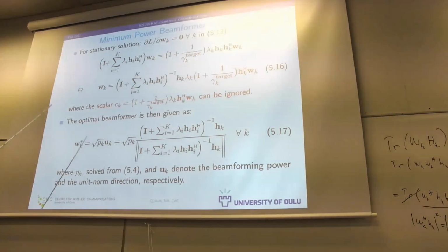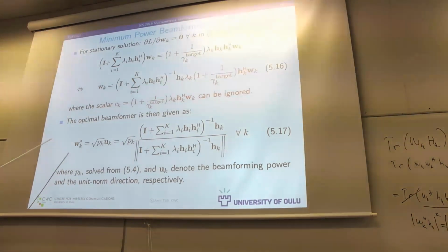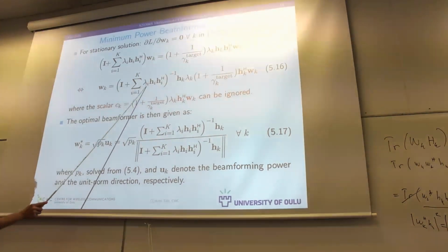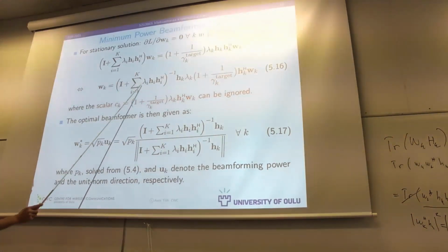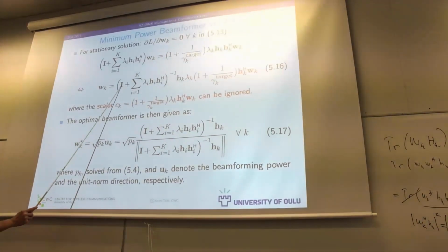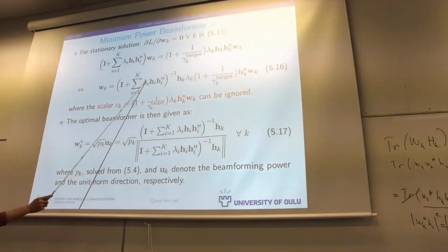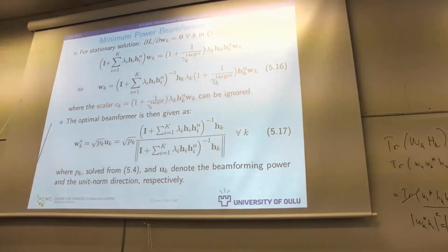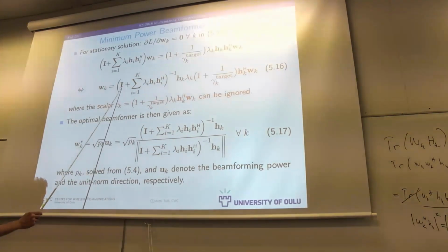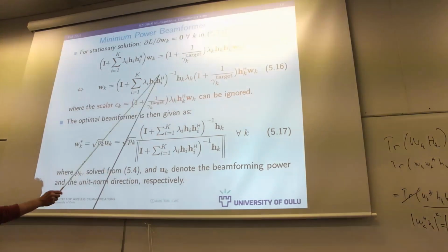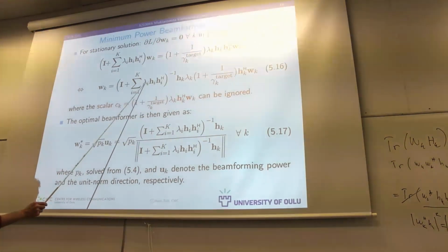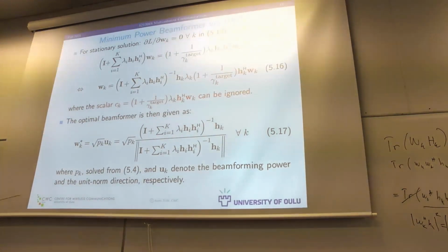It's kind of a regularized zero-forcing matrix, right? We have a regularization rate. We have an identity matrix, but we can also assume other terms appearing here. Well, we'll discuss the actual regularized solution later on. Anyways, it includes the identity component and then a rank 1 matrix multiplied by the dual variable for each user.